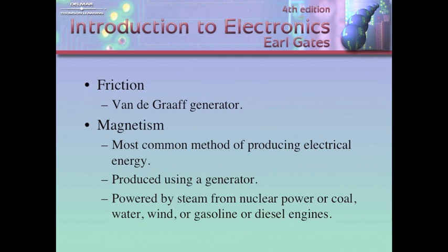This prevents you from walking across the floor, building up a static charge, touching a sensitive microchip, and damaging it. You'll learn a lot more about this next quarter, but it's very critical that you understand. That's why you need to be careful when you handle electronic components, because just wearing clothes, the clothes rubbing against your skin and your t-shirt, generates static electricity.